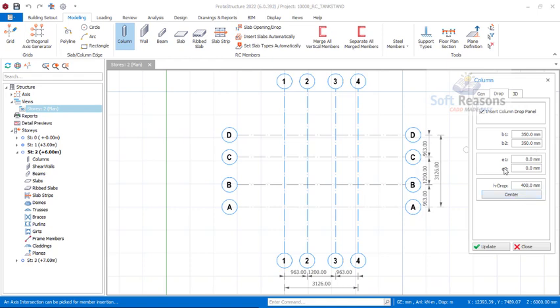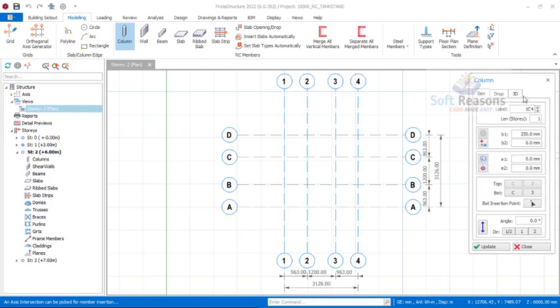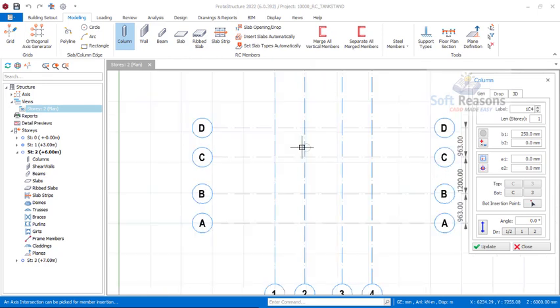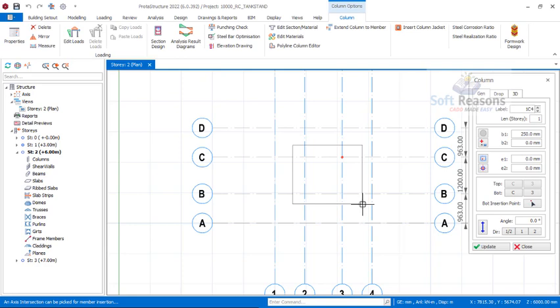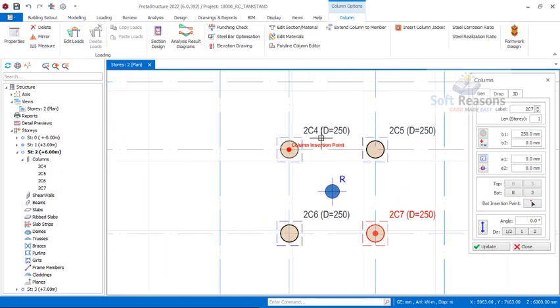So you click on the center to enable these eccentricities. Click on center, you have an eccentricity just like this. Okay, so with this now we have set all of that for these columns, the drops, as well as the length of the column. So we just click here and do a window over this four intersection point. Release your hand to have the column placed with the drops successfully.